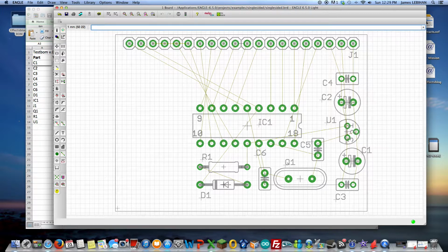Sometimes we may find that they're smaller than that, and in this case, with through hole electrolytic caps, I can spread the leads out a little bit, so I have a little tolerance there. With something like a ceramic cap or an IC or a jumper, I don't have that, so I have to be absolutely precise with this pin spacing. I also need to know the diameter of the holes so that I can make sure that I'm not getting a lead that is too big to pass through the holes. Okay, so those are things that we'll need to know before we go get the parts, and we can get that from the board itself or the drawing or other technical documents that you have describing that.